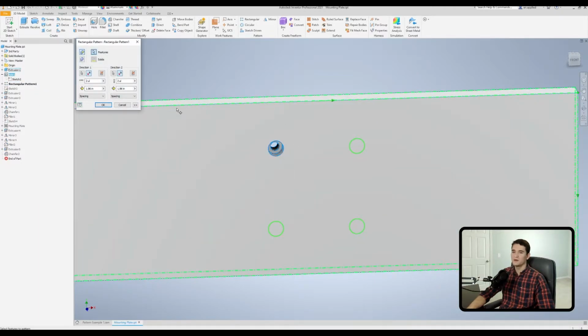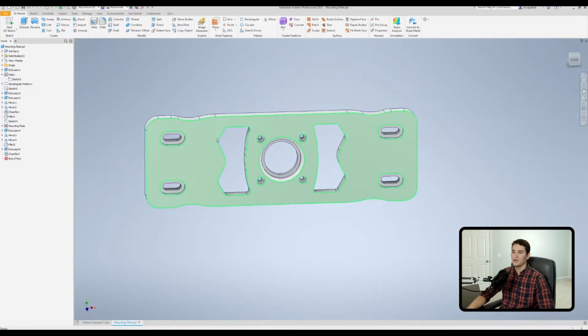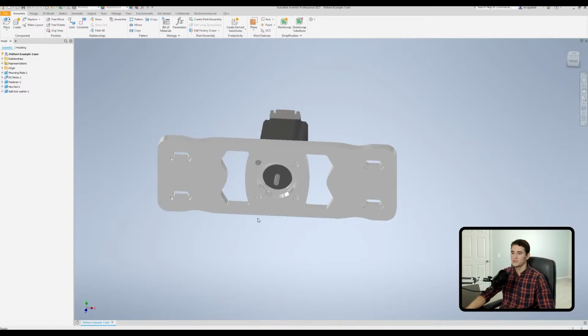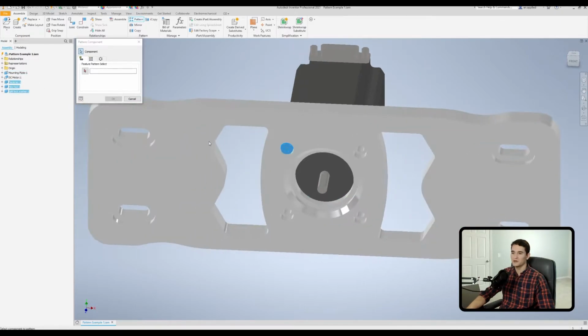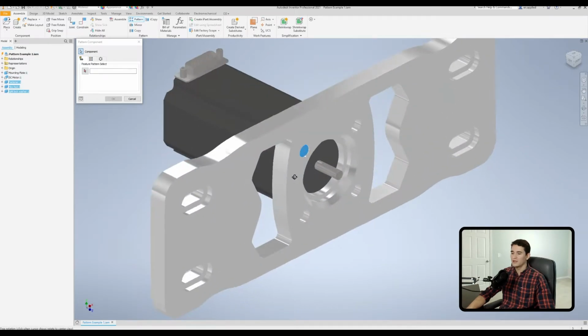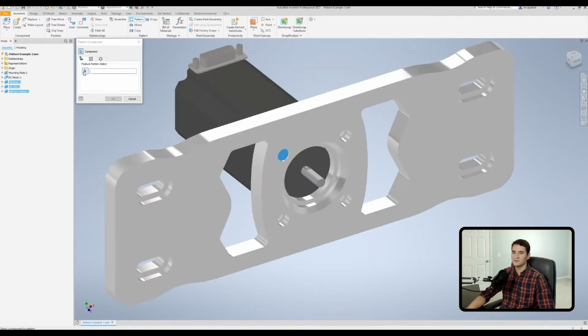Okay, so now that that was done, we can go back into the assembly and, like I said before, recall that feature pattern for our component replication. So let's do that. We'll just exit out of this. Okay, now let's go back to pattern. We'll reselect our components that we want. So I'm going to pick up the fastener, hex nut, and split lock washer. Okay, and so now that we have those selected, we'll activate this selection filter.